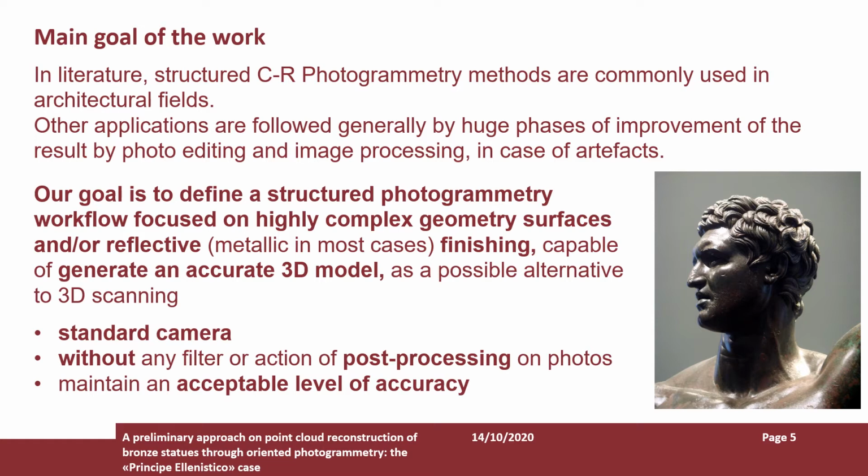Our target is the definition of a structured photogrammetry workflow focused on highly complex surfaces, like the ones we can find on a bronze statue, sometimes also with a reflective finishing due to the metallic nature of the statue itself. By this workflow, we want to achieve an accurate 3D model comparable to what we can obtain by 3D scanning.